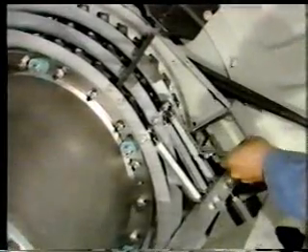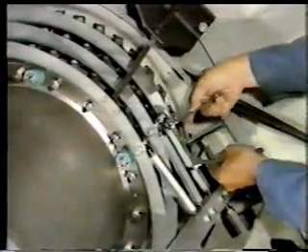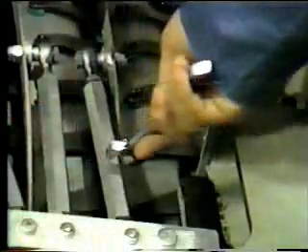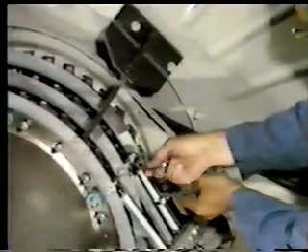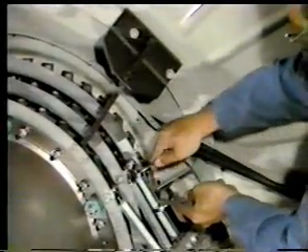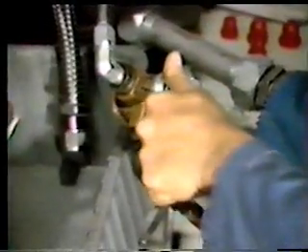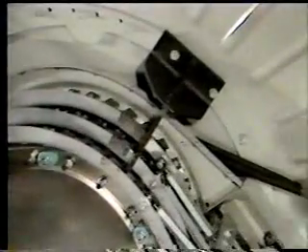Set the inlet guide vane ring to -35 degrees or C by adjusting the turnbuckle from the ring to the lever arm. Loosen the turnbuckle locking nuts. Then adjust the turnbuckle. Tighten the locking nuts. After you have turned the oil pressure off, reverse the position of the two oil lines leading to the actuator. Drive the vanes to the fully extended position.